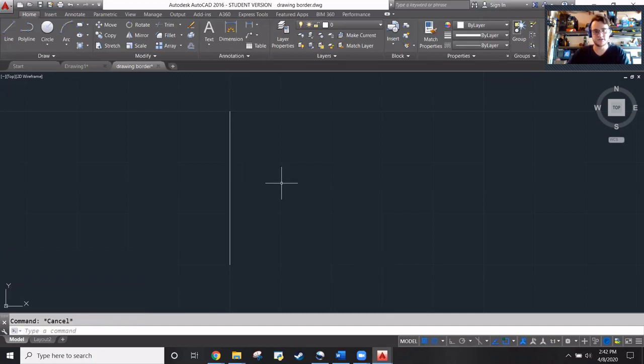You can do this 2 ways. Let me start over. Hit L for line, right? And then I'm going to draw one that's 3 long, and then you can either hit escape and hit L again, or you can just mouse over, and I'm going to get an extra line in there, but that's okay. And then I'll just select that extra line that I don't want and delete it. Right. Cool.